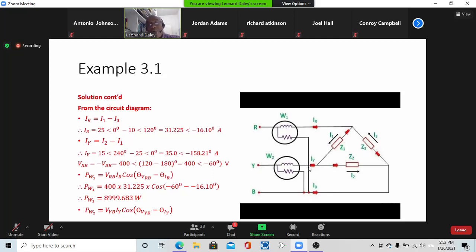Then we need also to find IY, which is flowing through wattmeter 2. So IY is equal to I2 minus I1, and that works out to be 35 at angle minus 158.21 degrees. All right, and remember we...